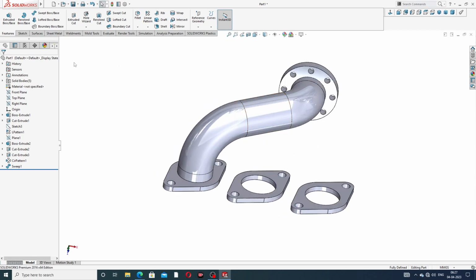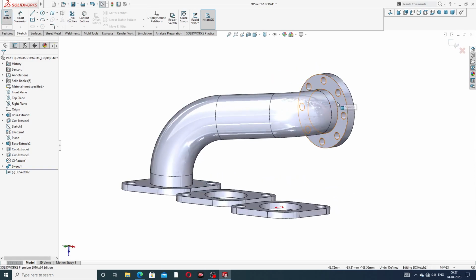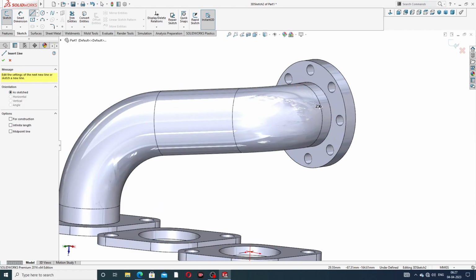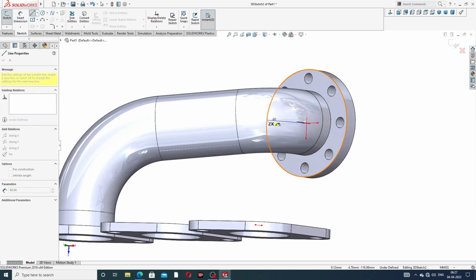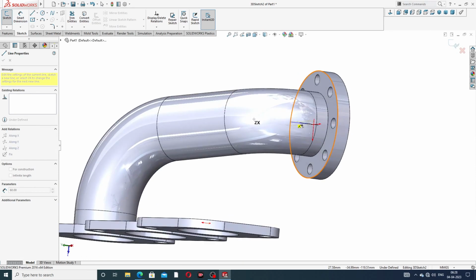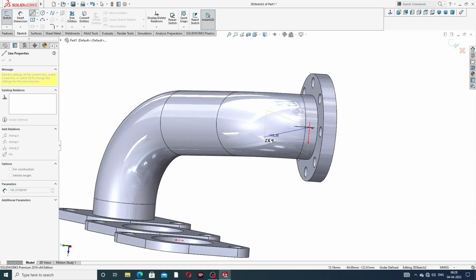Okay, and same here, next is drawing here, use a 3D sketch, and again drawing this, select this. Okay, line is selected here, and this is correct, but this point is vertical and not mentioned here, and this use press a tab, then use a vertical line, okay.